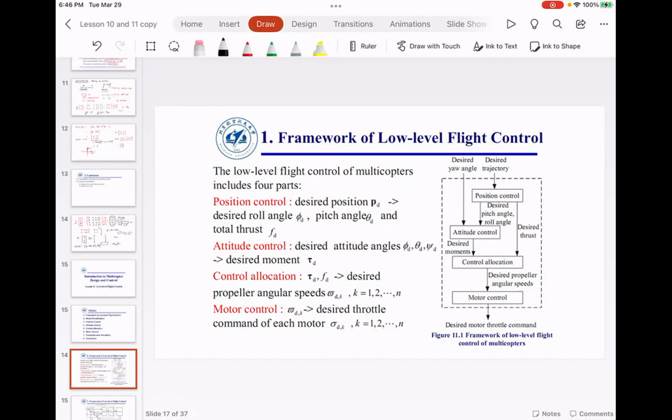So you want this quadcopter to go forward by some amount, by delta x. Here is how you will do it. You have acceleration measurements in the x, y, and z directions. You can doubly integrate acceleration to get displacement, but that is going to be super noisy. So how would you get an estimate of movement using the data from the optical flow camera? This camera is going to take pictures all the time.